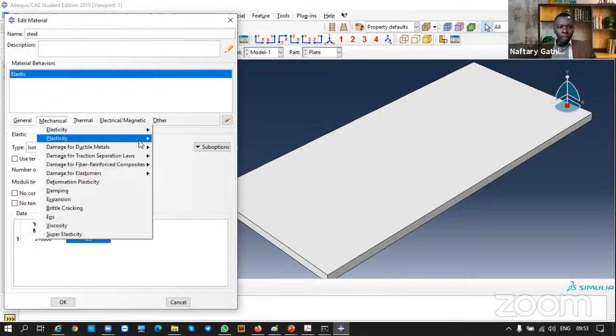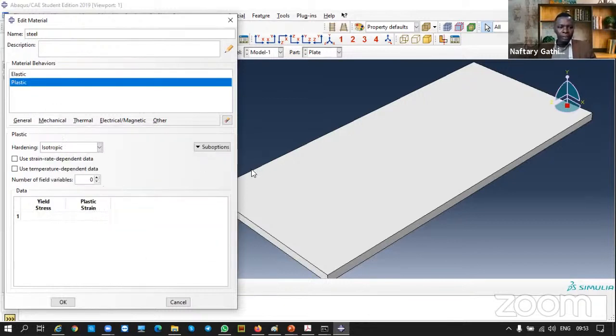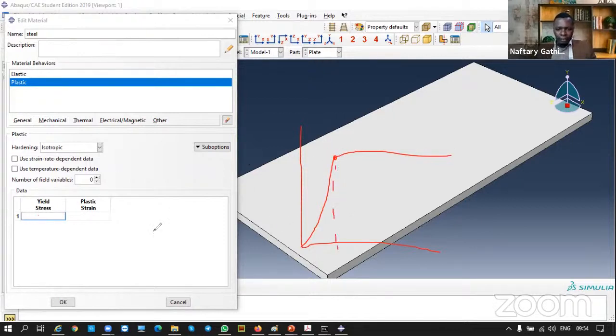If I wanted to do an elastic plastic analysis, what you call an elastoplastic analysis, I would have come to define the plastic material behavior again. I would have to define the yield stress. So what I'm doing here is elastic, plastic. I need to define the yield stress. If the strain maybe is something like 0.002, because it's 0.2%, let's say. Sorry.